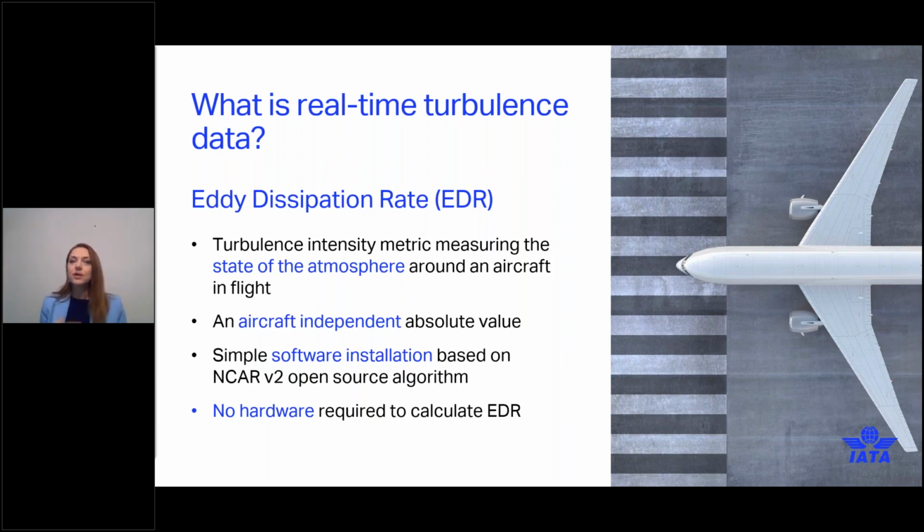The big aircraft such as Boeing 787, for example, crossing turbulence, which is measured as EDR 0.3, will probably experience light to moderate turbulence, whereas a lightweight aircraft passing through the same airspace where turbulence is measured as EDR of 0.3 will experience this as a severe turbulence. So EDR is an aircraft independent metric, but at the same time, the way it's impacting the aircraft is more subjective depending on its weight. So hopefully it sort of gives you an idea of how EDR works as a metric.